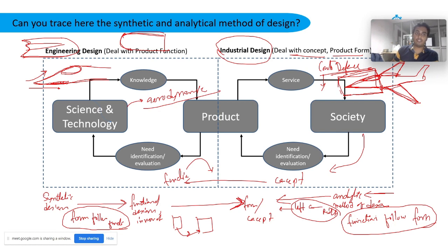There's a different design for the tip of a ballistic missile, and a different design for the tip of an aircraft, because you also need the requirement of having visibility. Okay, it is not like a missile, which can be just round or a dome kind of structure. So these are highly influenced by what technology is defined and what the requirement of aerodynamics is. Okay, so this is how you try to distinguish what drives a particular design.